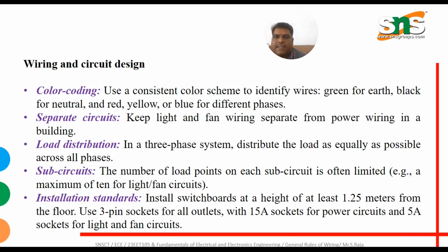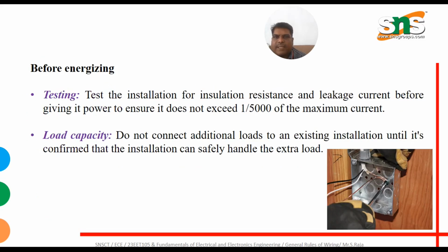Installation standard: install switchboards at a height of at least 1.25 meters from the floor. Use a 3-pin socket for all outlets, with 15 ampere sockets for power circuits and 5 ampere sockets for light and fan circuits. Before energizing, that is, before we give the power supply, we need to provide a testing. Test the installation for insulation resistance and leakage current before giving power, to ensure it doesn't exceed 1/5000 of the maximum current.